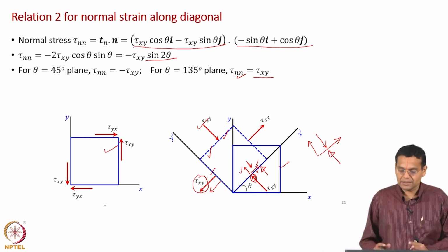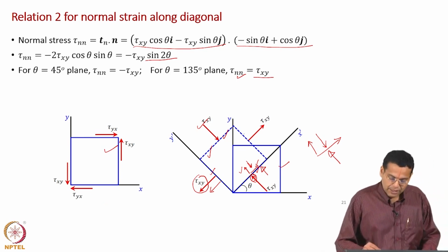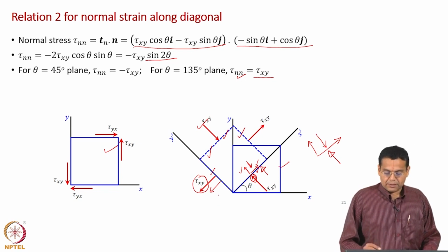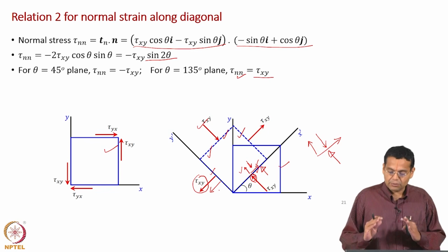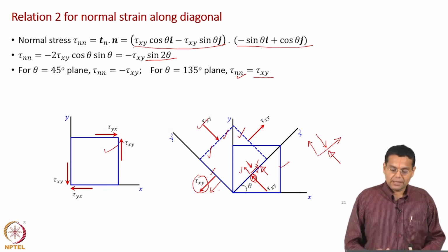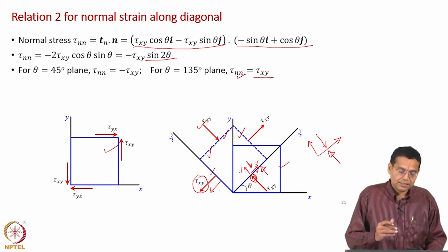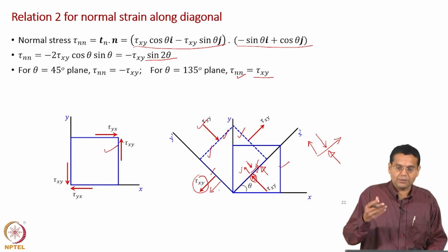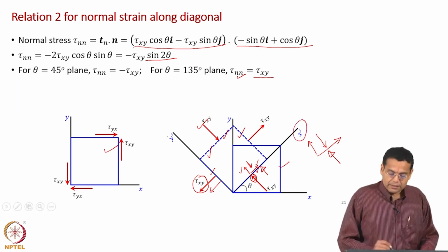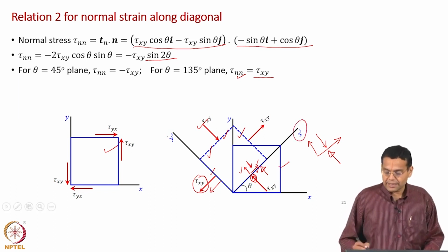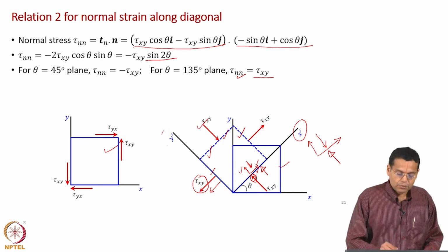There are no shear stresses, that is what you see here. When you look at this dashed boundary which represents the rotated stress element, there are only normal stresses. Those normal stresses have been expressed in terms of tau xy values, but in this rotated configuration there are only normal stresses, and the new axes are denoted as x dash axis and y dash axis.